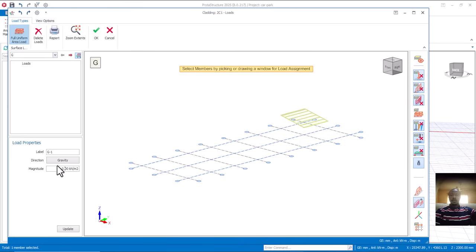So now coming to this place. This unit point to 1, but most of the times we use 1. Now apart from that, depending on the location also, because there are locations whereby they experience a lot of snow, in that case the value here will be different. So let me now choose 1 kilonewton per meter square.